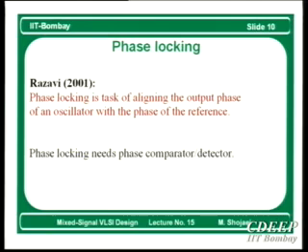This means you need a feedback loop after all, right, to generate this. And if the loop gain of this feedback loop is very high, that phase error approaches zero. Therefore, when locking happens, the delta phase, or difference between two phases, is close to zero. That is another interesting point: not only am I able to develop a constant phase, but that phase is almost zero.